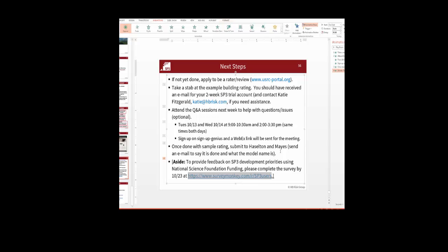Yeah, and it depends on what the application is. Once the simplified method is in place to take care of weak story, soft story, that handles more of the behavioral aspects. In terms of the specific component fragilities, one option is to select the component fragility that's most similar to the one that you have, in terms of what you think the damage, repair cost and consequences would be, to give you an estimate of where you're at. But it really just depends on the application as to whether that's a good estimate or not.